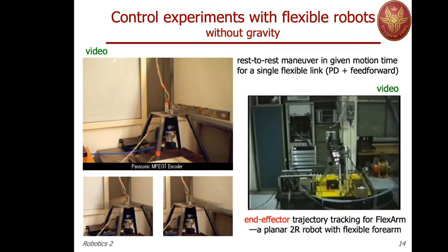And we have addressed and solved a number of other control problems on this arm, in particular on the second one, which also has a critical feature for those of you who are more interested in control. The end effector of this arm has a non-minimum phase characteristic. So when we talk about inversion control or feedback linearization control, this is not possible for such a structure.